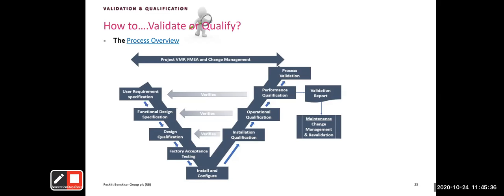Working in line with the operator's manual to say, you operate this, you get this response, you check, and you confirm that the response is satisfactory. Where there are deviations, you raise that deviation and you ask the equipment manufacturer to confirm whether those deviations can be closed out or not. Now, once you're done with all the operational qualification checks and you have no deviations, you move on to performance qualification. Now, in performance qualification, what do you check? You are checking for accuracy of responses.